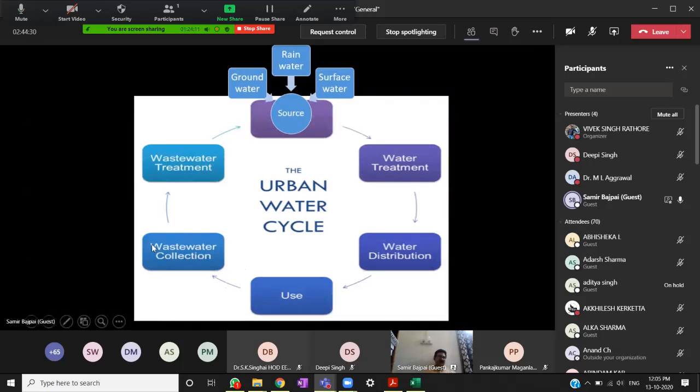Wastewater having human excreta in it is known as black water. So what we are doing today is mixing both grey water and black water. Actually, grey water is not that difficult to treat. It can be treated at a small scale, while black water requires expert treatment. So we mix all the wastewater coming out, and then we need to go for wastewater treatment. Why?